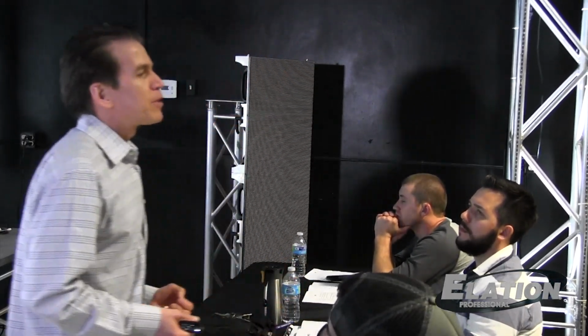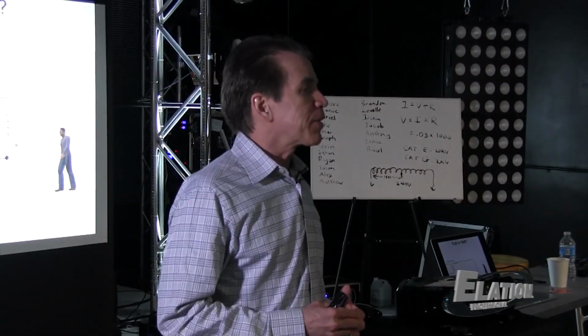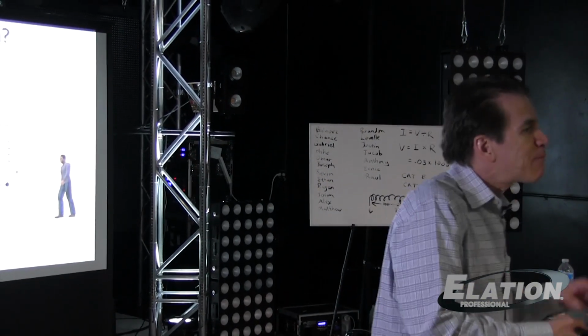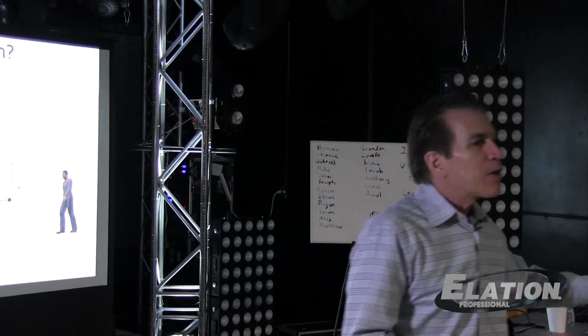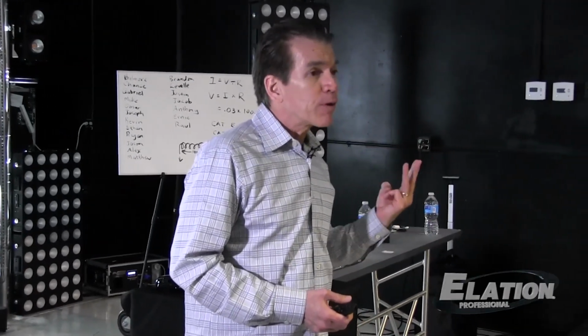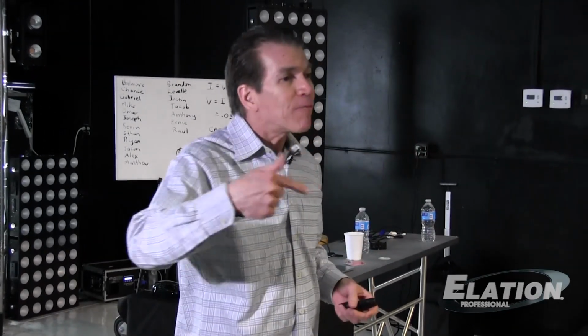But sometimes there is. How does that happen? Through what's called mutual inductance. If you have a green wire next to a feeder cable, and the feeder cable has, I don't know, 100, 200, 300 amps flowing through it, there's a strong magnetic field around that feeder cable.